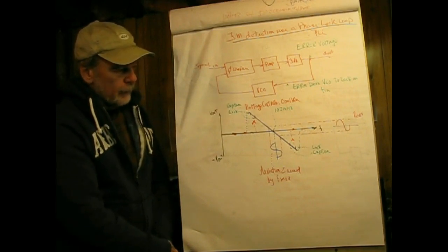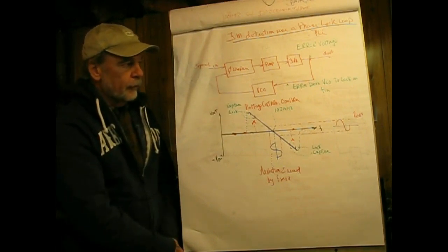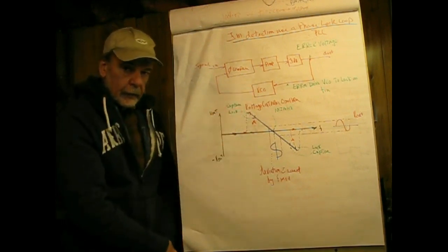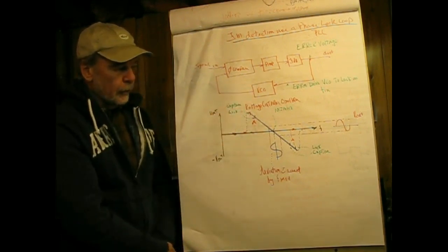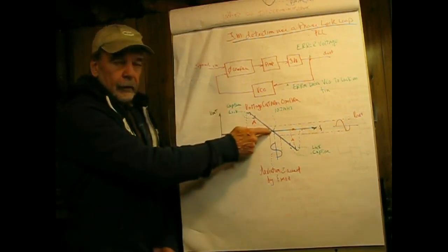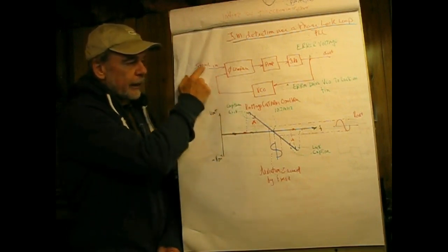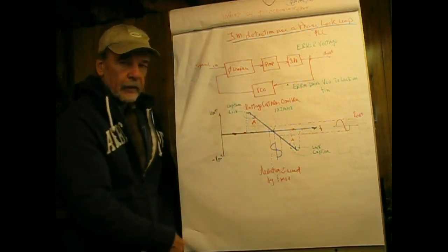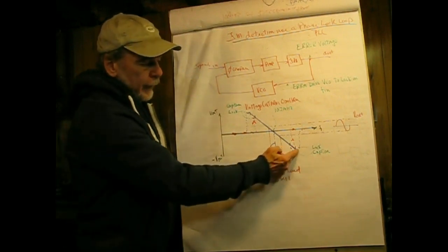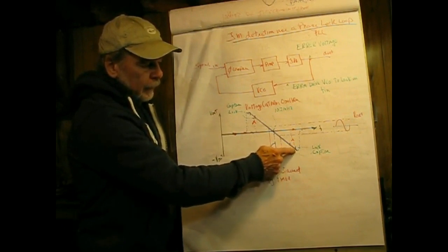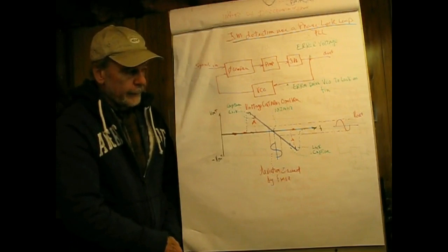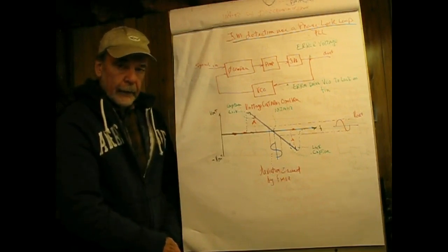So the claim to fame of phase lock loops is that they're very simple. They don't have any tuning other than RC, as in resistor capacitor tuning of the VCO, and once you achieve lock, ideally in the center, because you want the VCO to be center of range relative to your maximum deviation, you're in good shape. Now if the thing is over deviated and exceeds the capture range, then the phase lock loop is going to lose lock, and our output signal will look very bad.